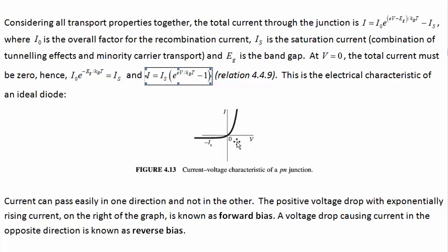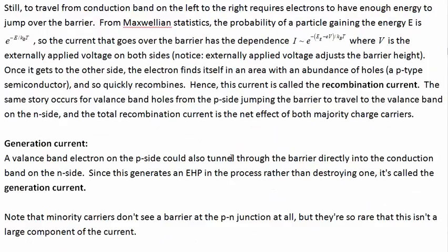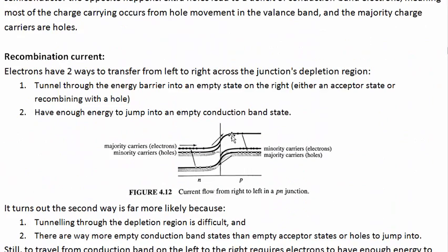So the forward bias region on the right here, where you apply a voltage to lower that relative energy barrier, means that you can get a lot of current going. So there's a lot of charged carriers here. If we make this barrier low enough, they can just fly right across, and there's very little barrier for conduction.